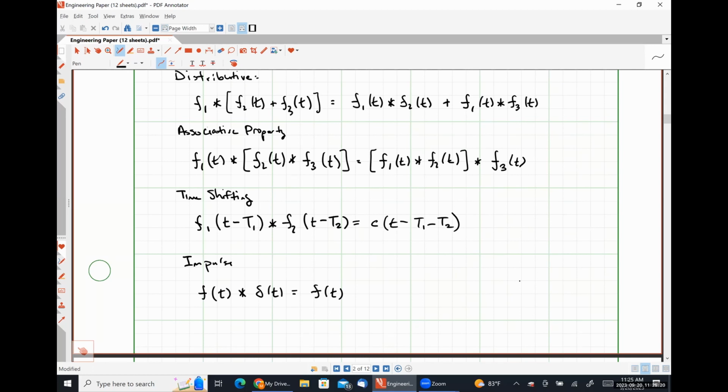So effectively, it means that whatever we choose as t equals 0 is the turn on point for our system. So we can't have any stored energy or anything like that prior to t equals 0. We can't realize non-causal signals either, meaning that we can't observe a signal until we turn it on. So all of our definitions here, ranging from negative infinity to positive infinity, don't actually make sense for us, because in our application, everything is going to start at t equals 0 when we turn stuff on.